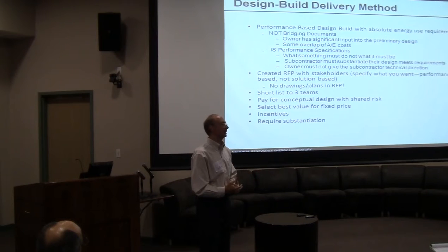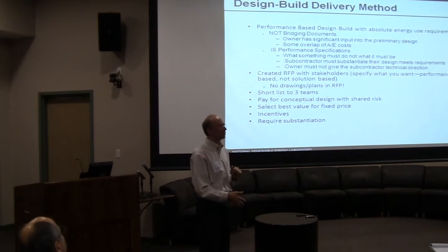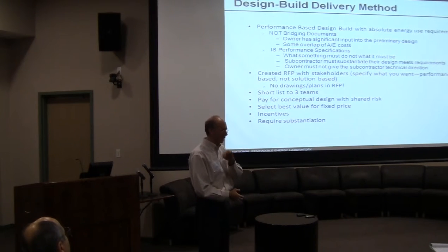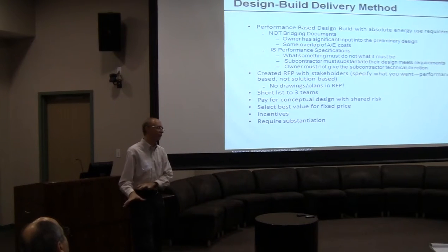This building has twice the exterior skin of a conventional square box building. Well, how did they do that and not kill the cost budget? Right? They pre-engineered these precast concrete panels with insulation integral, glass included, everything done, smooth finish on the inside so they didn't have to drywall, and they hung them on a steel frame. And every panel's identical. And so they were able to very carefully control the quality off-site and bring that stuff to site. So they had to bring that innovation, which I don't think you get if you have to put a bid in the middle of it.